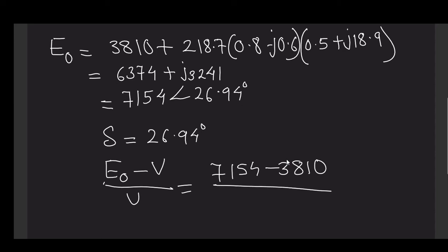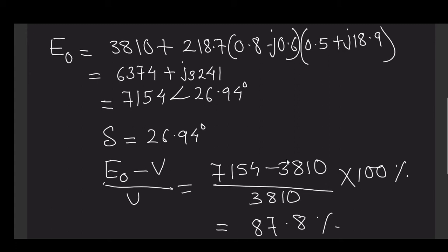as I said in the third semester, Mr. Ayushman Khurana made a very good observation. He spotted a calculation mistake. So you will also please calculate by yourself, and in case of any problem, please get back to me so that I can also help you. So this is for our open circuit test, that EMF method. Sometimes it is also known as the method of synchronous impedance. So this gives us a regulation value of 87.8.